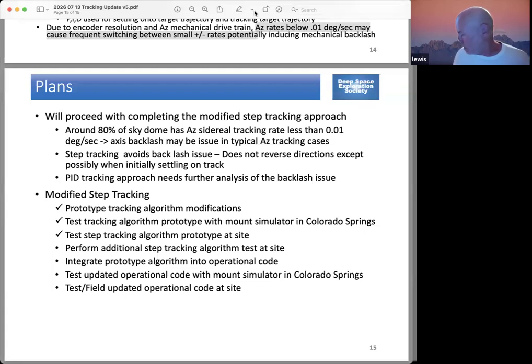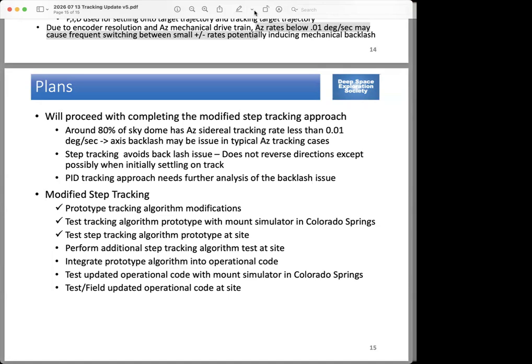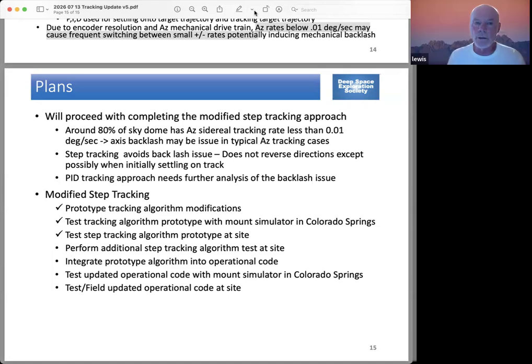It's a 5,000th of a degree. Okay. So the 12-bit encoders are slightly under 0.1 degree, and the 16-bit ones are at a 5,000th of a degree. And one of the things I have noticed is I never see any jitter in the last bit on the encoders, so they seem to be fairly solid.